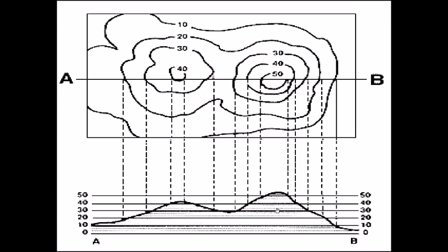So like we see over here, we have two hills, and when you draw the contours, these hills are shown in a section view. That means you're looking at them from the front in actual. So they'll have a conical shape, and that's why you have a contour which is circular, and two hills, so that's why two sets of circles, and then you have bigger irregular circles since the elevation then gets similar with both the hills.